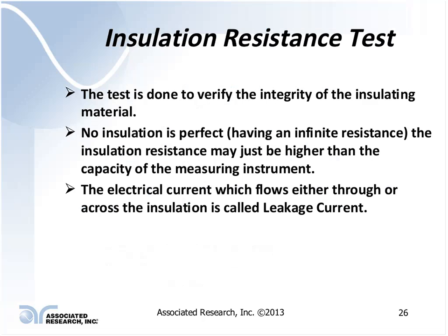There are multiple types of touch current test. Depending upon the type of product, you may be doing an earth leakage current, an enclosure leakage current, a patient leakage current, an applied part, mains to an applied part test. So there are multiple different types of tests that all fall in this touch current type leakage current category, and they get involved into quite a few different switching configurations. Unfortunately, that's a whole webinar in itself that I don't have time to get into today.